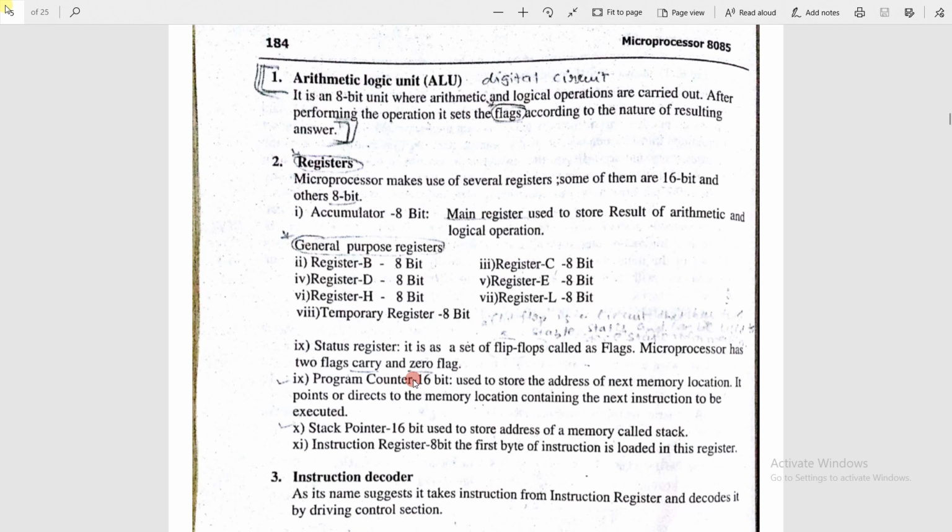But the next instruction is to jump to some other memory location and execute those set of instructions which are in series on that particular memory location. Once executed, it should come back to the second instruction again, or the third instruction, not the second, the third instruction of the current set of instructions. So what is happening?